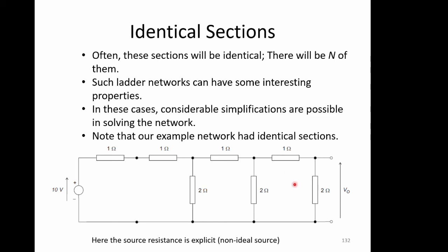So this is the same as we had before, but this time we've split the source resistance into two, because it was a 2 ohm resistor before. We've just said that's the equivalent of 2 1 ohm resistors in series, and now you can see we've got an ideal source here, and then we've got 3 bits of upside down L-shaped ladder, would be one way of viewing it.